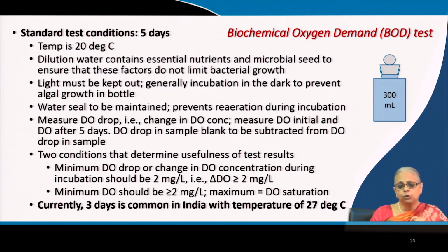In fact, there is one more point that I need to mention, that once the dilution water is added, it's also aerated. So the aeration is done prior to filling the bottle to ensure that this dilution water is completely saturated with dissolved oxygen. So when it is added and the water seal is created, no further re-aeration is allowed during the incubation period of 5 days.